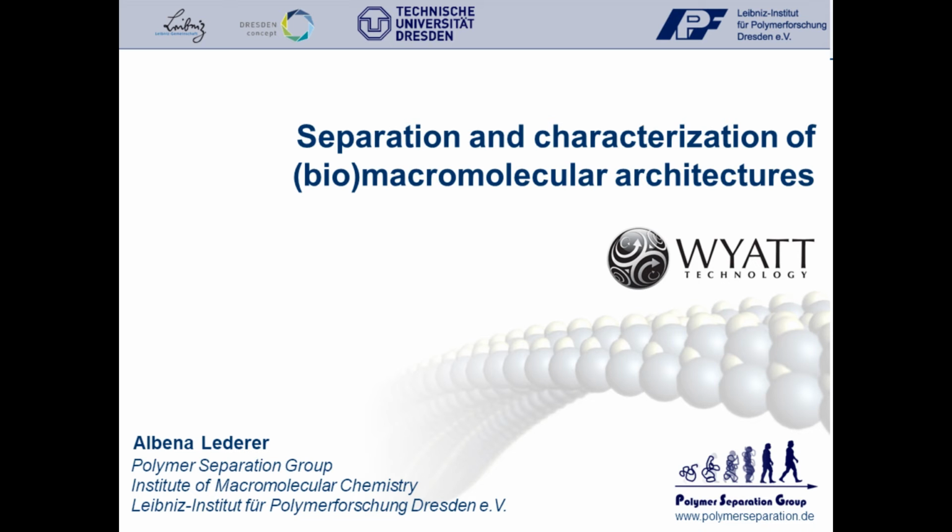What is not really trivial is to combine field flow fractionation with viscosity detection. There are only few results reported, as far as I know, on this topic, and this problem comes from the pressure which is produced during the focusing and elution phase during the FFF fractionation, which is changing, because the pressure is actually the parameter which is measured in a viscosity detector.